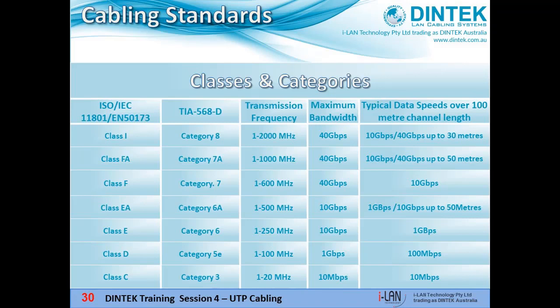The transmission frequency rating of the cable is just one of the criteria the cable needs to achieve to meet that standard for its class or category, and transmission frequency doesn't necessarily play a role in its bitrate performance. The standards specify qualities for each category of cable like wire gauge and composition and how it needs to be constructed to handle impeding factors like EMI, echo cancellation, equalisation, DC balancing, near-end crosstalk, far-end crosstalk and so on, and that's with our twist rates, wire spaces, screening and shielding and so on. All of these factors combined give us the cable's performance.